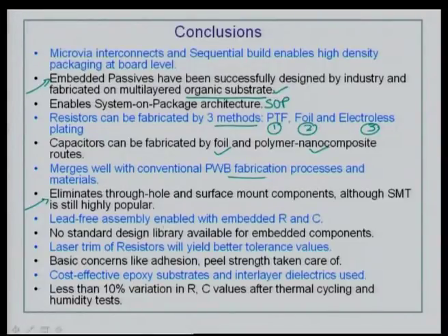Basic concerns are adhesion, peel strength, which you have to take care, and cost effective epoxy substrates and interlayer dielectrics have to be used, and you have to look at tolerances after thermal cycling and humidity. So, this concludes the chapter on embedded resistors and capacitors.